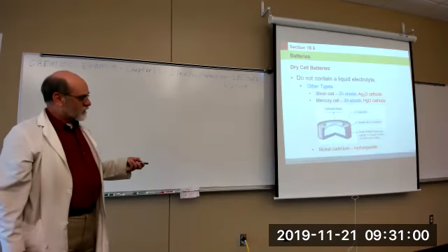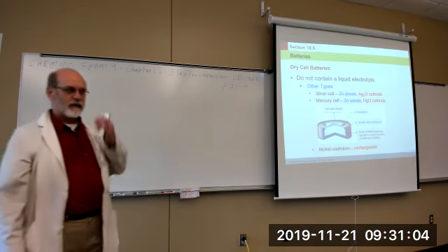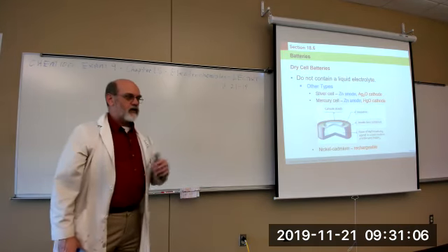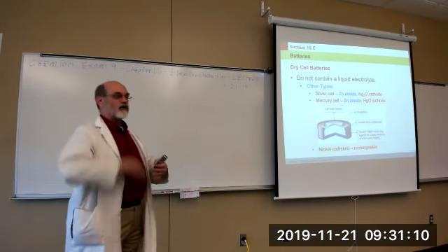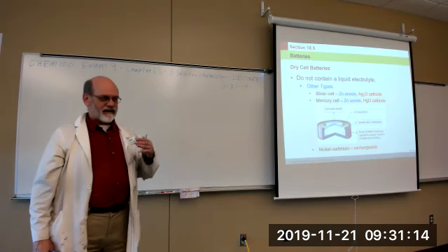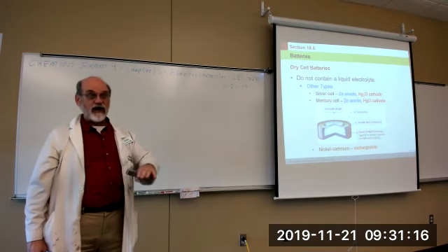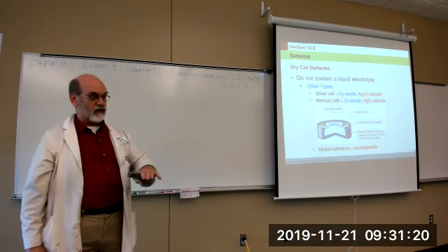So these are not used very much anymore because they have a memory effect. In other words, if you discharge them, say halfway, and then recharge them, they reset themselves. They think that that half charge level is the bottom of the barrel. They think that's zero, so they won't go any further below that.